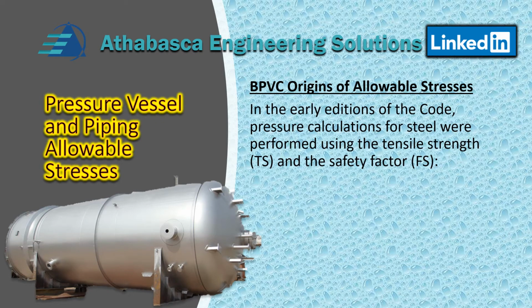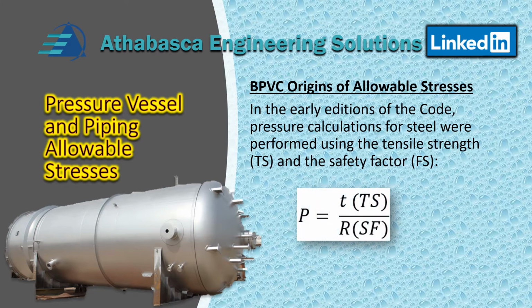So in the early editions of the code, the pressure vessel calculations for steel were performed using the ultimate tensile strength, the UTS or TS, and a safety factor of Fs. The equation looked like this. So where T is the thickness, the tensile stress, R is the radius, and the safety factor is shown below.